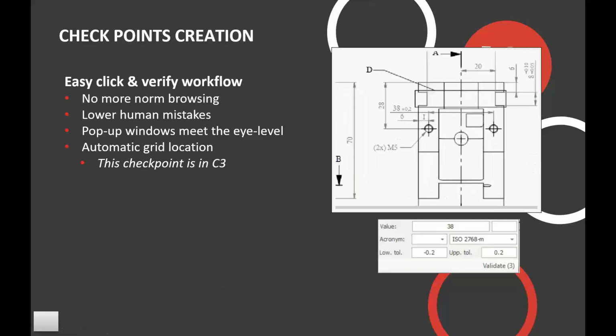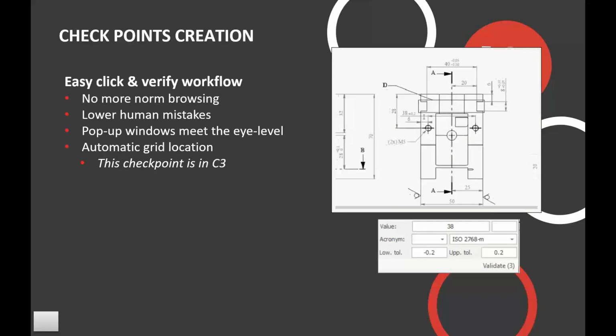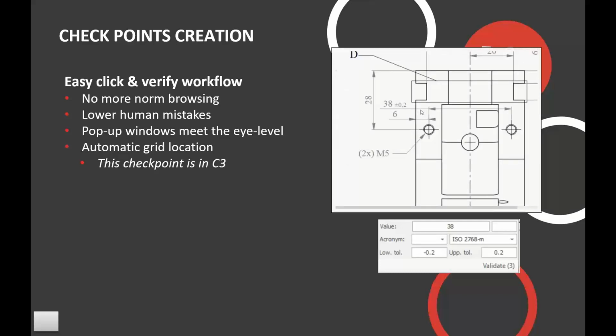Now let's take a look just quickly here at how you capture something. Here you can see we're zooming up, right-clicking, going to dimension selection, and literally you draw a window around it. This creates a balloon. This captures the values. It captures the tolerances, and you're done. It's literally that simple to capture. This is the way you capture it, whether it's a PDF document. If it's a DWG-DXF, you can actually just click directly on the image, or pardon me, on the number.